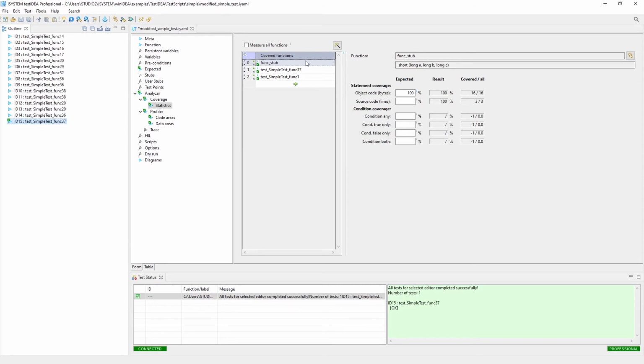Okay, so that's basically how the coverage works. So the other way, again, this was taken with the actual trace mechanism. The other way to set it up is using a feature called slow run. So if you don't have access to any trace interface, you can use a slow run feature. It does run the code very slow. So what it does is it single steps through the code and collects data similar to what a trace would